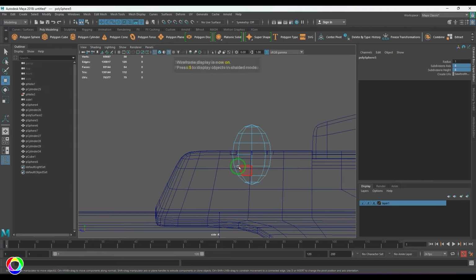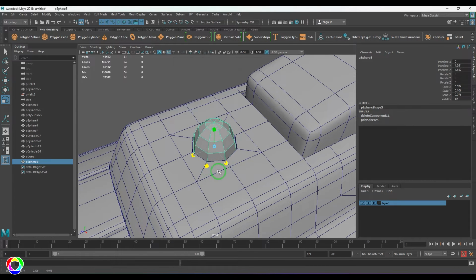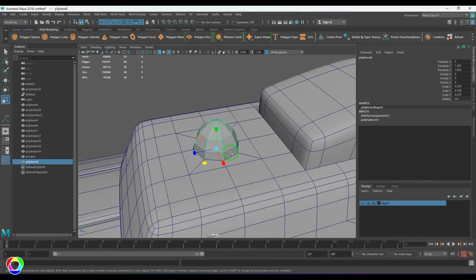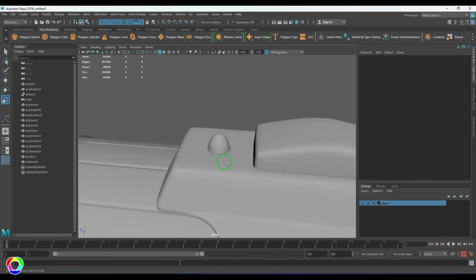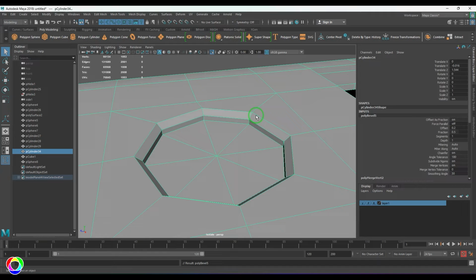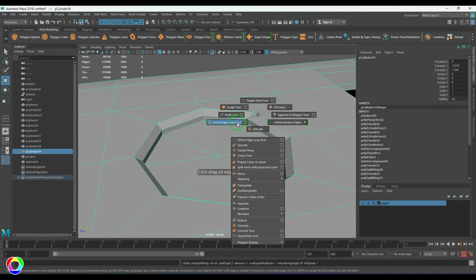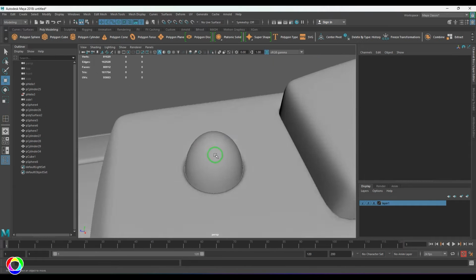Select those faces, delete those faces like that, and then when I apply smooth, you should get this kind of hole there. Now I'll be adding some lines. First I'll be selecting this, bevel it. Okay, one here and one there. I just want that gradual roundness. So yeah.